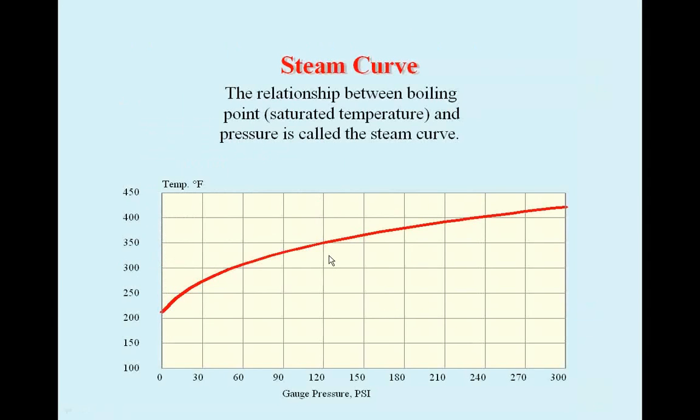What they're trying to accomplish with this is keep the discharge close to the steam curve. You don't want a whole lot of subcooling, as we mentioned earlier, and you don't want an on-off, where you run out to here and then up. You've got to have a little steam pass through, and then it cools off, and then up. You don't want that type of discharge characteristic.